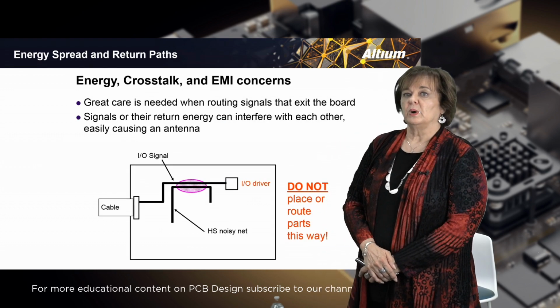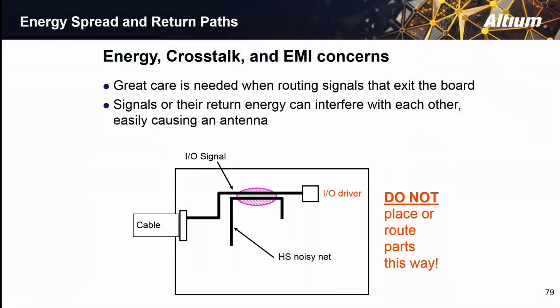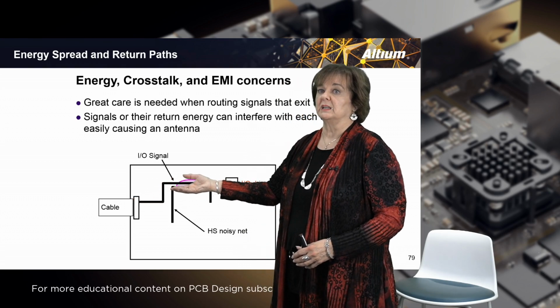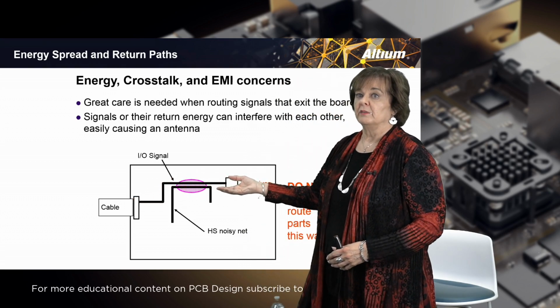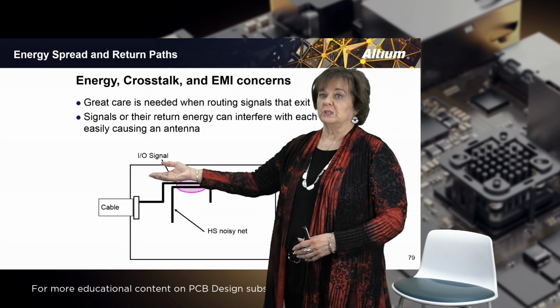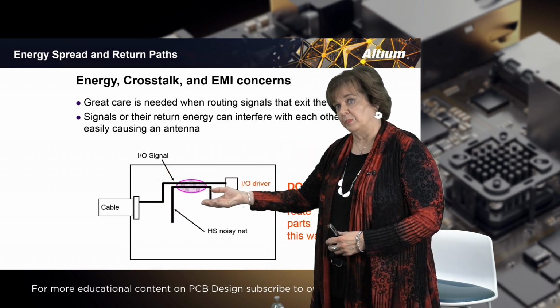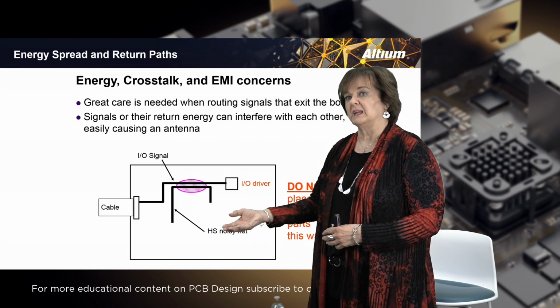Here we have an issue where we're dealing with I/O parts and signals, and we have an I/O driver that's been placed poorly, and it's way across the board from the cable that it connects to. And in doing so, there is a long trace that has to make a connection from one to the other. That I/O signal has a great potential for picking up noise from anything that happens to be nearby.